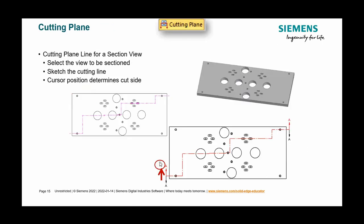Now, another nice feature that's available is the cutting plane. Cutting plane is used for creating a section view of a model, and we'll talk about section view next after this. You can create the cutting plane by simply sketching the cutting line, right? So you're telling the software, okay, I'm going to be viewing from here to here. In this example, we used a staircase, like a zigzag type pattern. And you can create the cutting line however you want. It can be completely straight, horizontal, vertical, or like you see here on the screen.